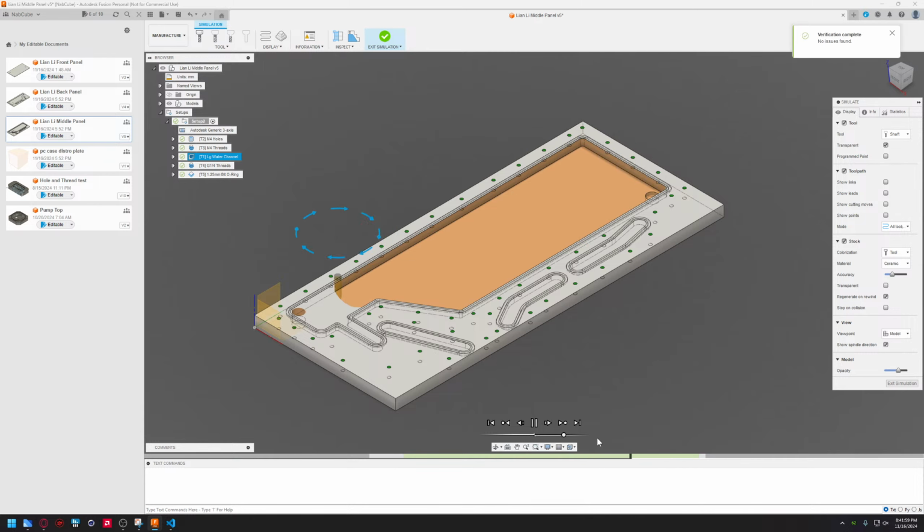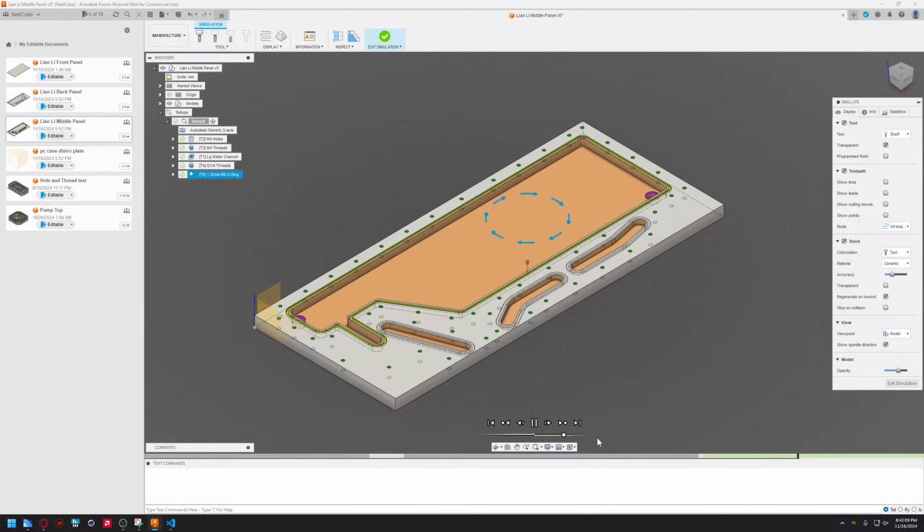When I start this, I'm going to see, I usually haven't ever done it where it does full adaptive like that. On my jobs, I usually do a regular raster where it follows in here, goes around and continues to raster all the way around till it gets to this outer edge, and goes like 1 millimeter down, which usually takes about 8 passes.